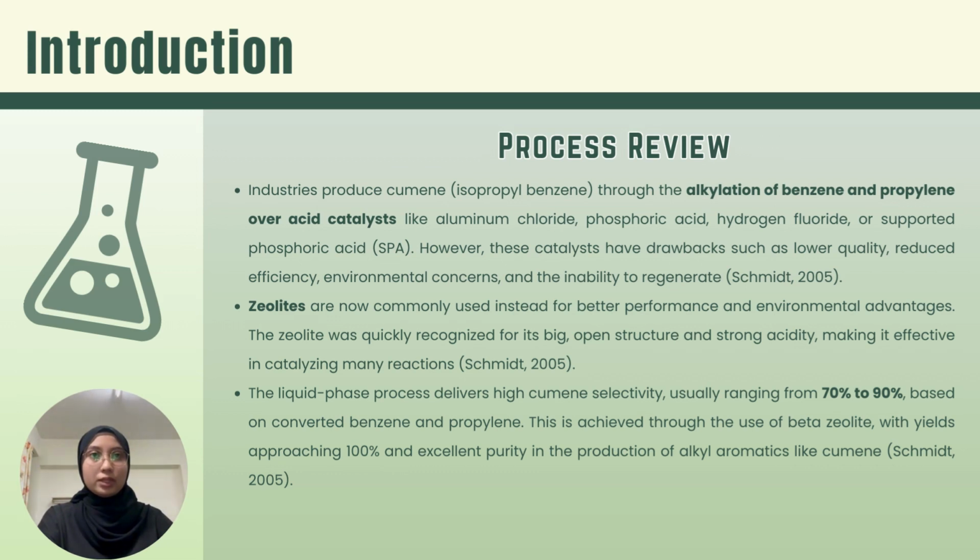However, zeolite have emerged as a superior alternative due to their open structure and strong acidity. The shift to zeolite catalysts enhances performance and environmental advantages. In the liquid phase process using beta zeolite, cumene selectivity ranges from 70% to 90%, achieving yields close to 100% with excellent purity in the production of alkyl aromatics like cumene.